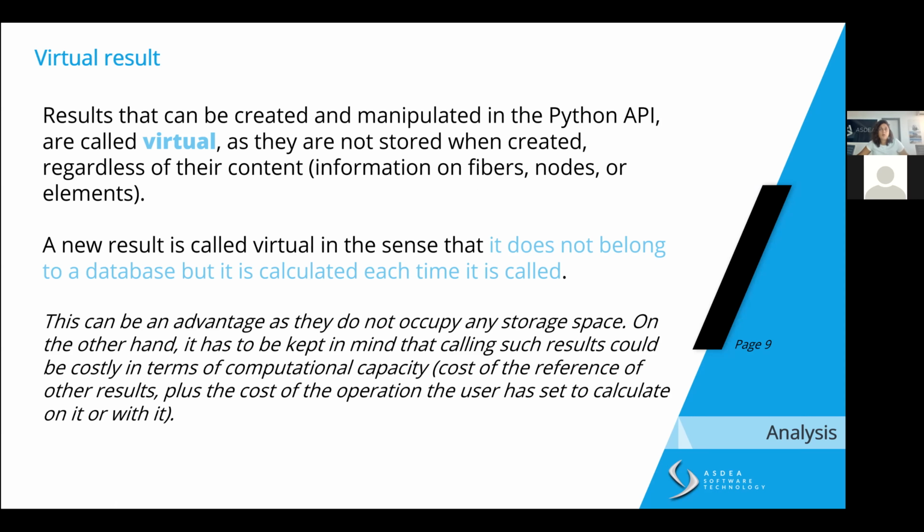This is really important because maybe you go a long way trying to create a lot of combinations of load cases, and then in the end you close the file and you lose them all. And maybe you did not save your script each time to create each combination. So it's an advantage because you don't need any additional storage space for this kind of results. You can create as many as you want and they will not load on your computer, but it could be costly in terms of computational capacity if you need to ask for them numerous times and they are calling many other results to be computed. So just be careful when you use them and keep this in mind.